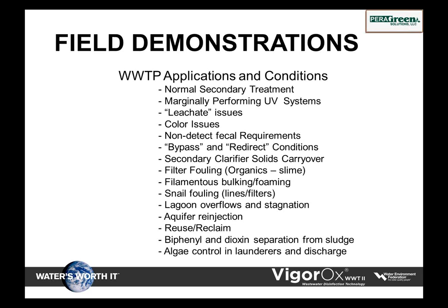We found also recently in New Jersey, we've looked at biphenyl and dioxin separation from sludge. They're finding that it's very favorable, so we're doing extensive studies on that. The last one is algae control and launders. I'll show you a picture of one of the facilities, and I don't have an after picture, but what it did, it cleaned all the launders up. It also cleaned the overflow of weirs and kept the algae from growing.